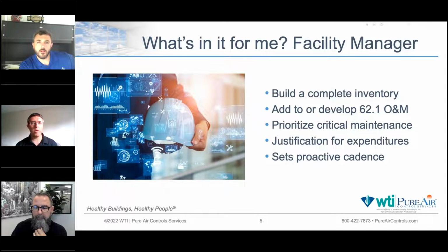So we get a call, we come in and we're looking, and first thing I do is start looking at the ductwork, and I see this debris scatter, and I look at the duct otherwise and say, wow, it was a good job, a good cleaning. Has VAVs in there. VAVs look good, just again, settled debris. I go back to the air handler, and it's in there that I find, in a kind of tough to access location, where there's sound attenuation. And what happened is, over time, debris built up in the sound attenuation area where you have these little holes, little gaps, perfect spot for debris to accumulate.